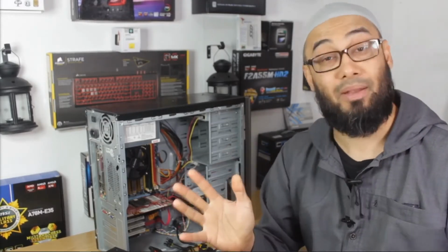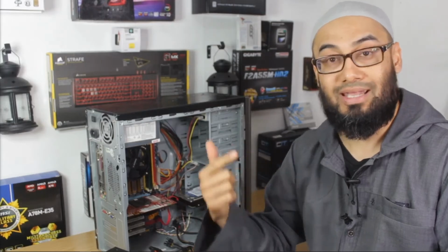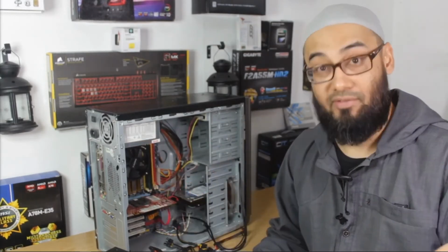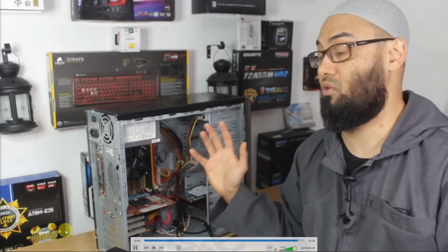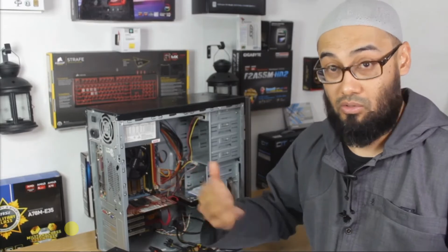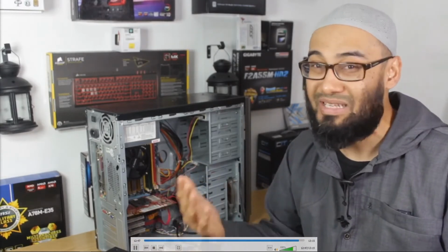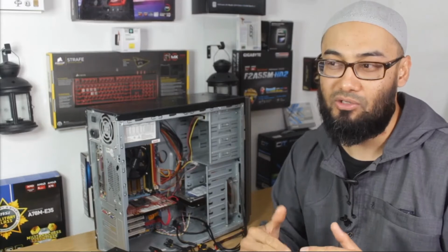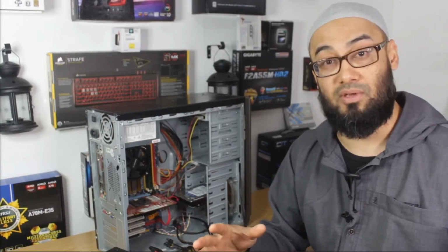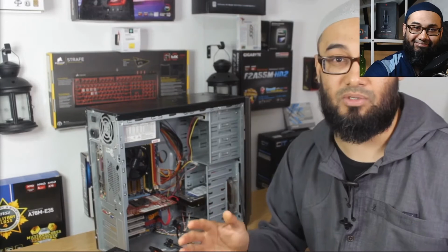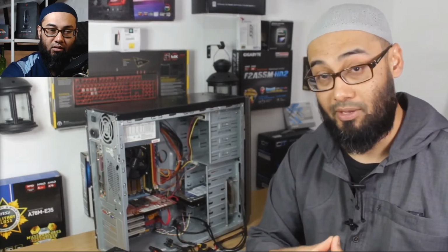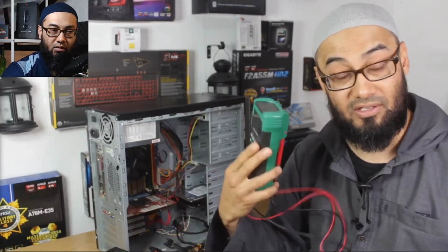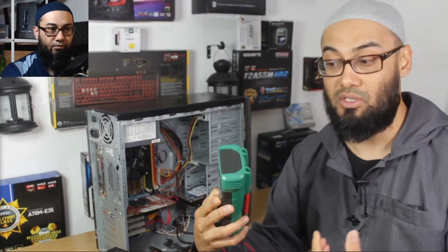What can happen if you're using a bad power supply? Obviously it can take out some of your other components, but even worse, and I've heard, I haven't had personal experience with this, it can set something on fire, even your whole PC, and obviously cause damage to yourself or people around you or even property. So it can be dangerous, although the rate should be diminishing by now, because hopefully most of you will not be using dodgy, cheap power supplies. So the advice is, if you're going to get a power supply to test, get a branded one, get it from a reputable seller with a very good warranty period, and it's always a good idea to have one of these, so you can test them even on purchase to see whether it's functioning properly.